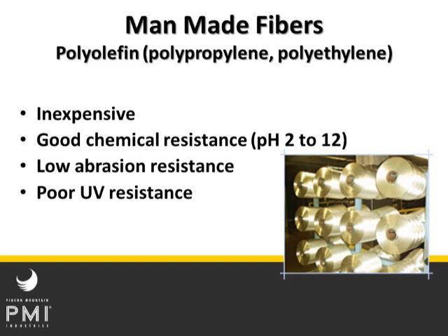It has a great chemical resistance range, pH 2 to 12. So if you were looking for something to lower yourself into a vat of acid, then I guess you might choose your polyolefin. Just make sure that it's not hot acid when you're doing it. But I hope people aren't lowering their friends into hot acid anyway. It has low abrasion resistance and poor UV resistance.